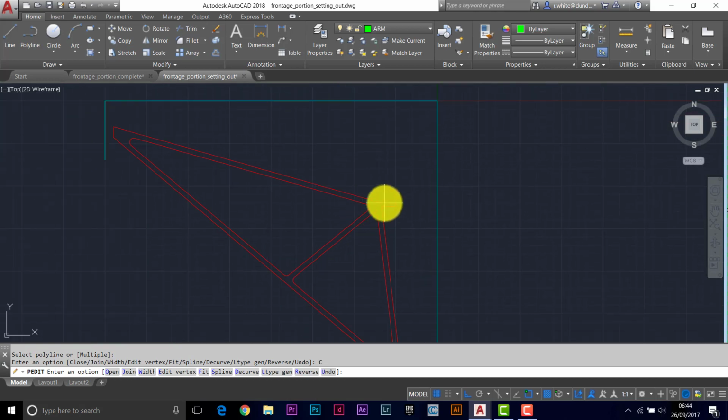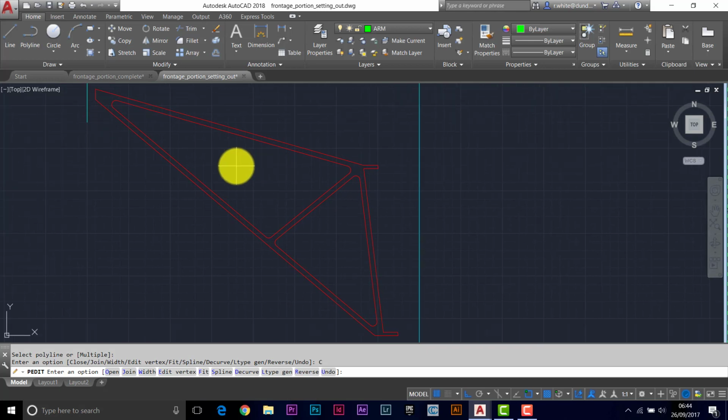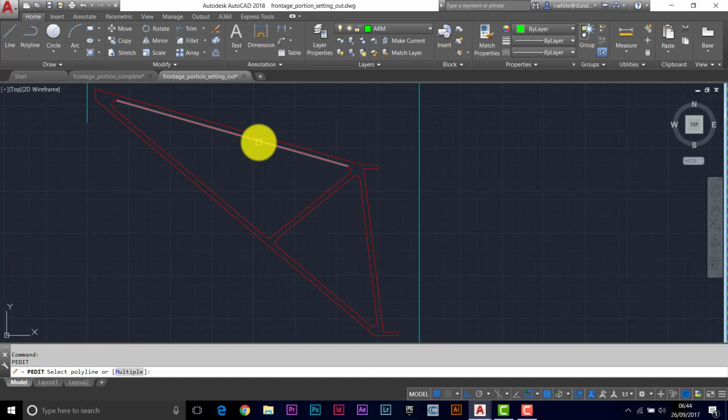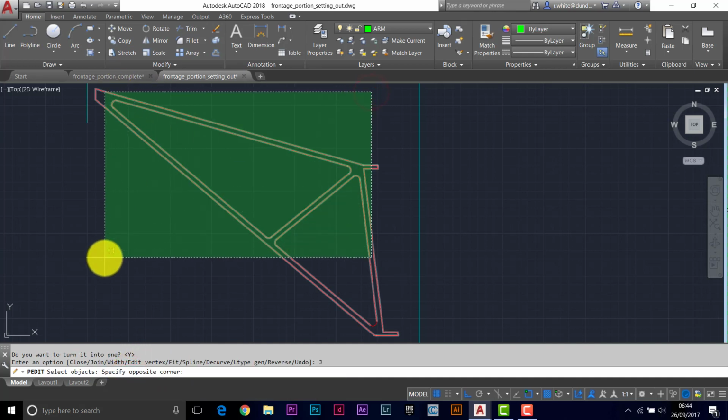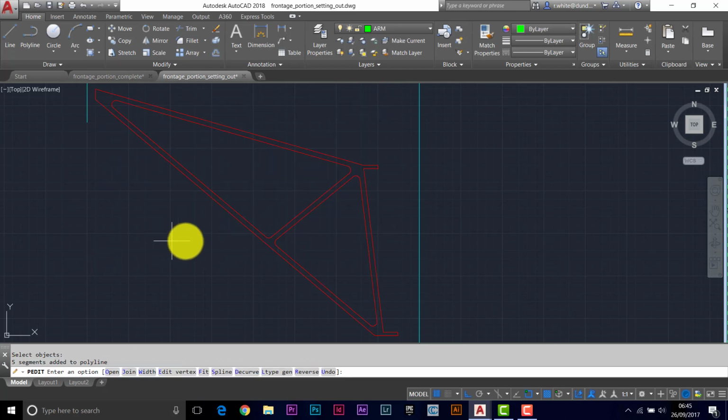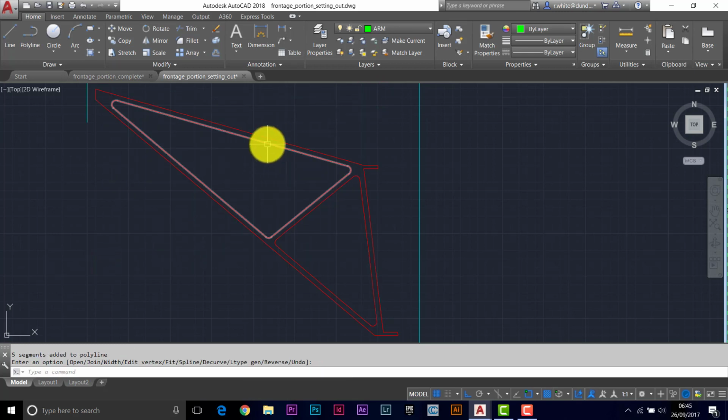Okay, so that's now extrudable. We've got to do the same with these, but these already appear to be closed shapes, so we shouldn't need to do any of this bridging on the internal triangles. So enter to finish the last pedit. Start that again. Enter to bring back pedit. Pick a line. Do you want to turn it into a polyline? Yes. Press enter. Join, and we grab everything inside now. Enter to finish. Enter to stop the command.